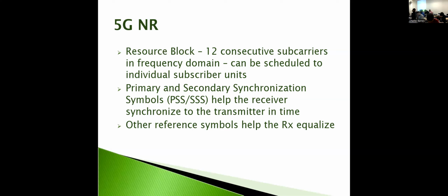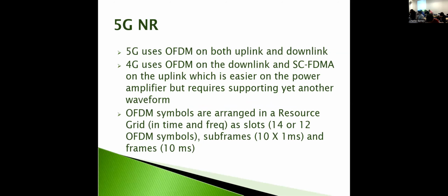There's also primary and secondary synchronization symbols. We call those PSS and SSS, and they are in that overall frame. As we mentioned, that frame is 10 milliseconds long, and that includes a whole bunch of OFDM symbols, organized in slots and subframes.